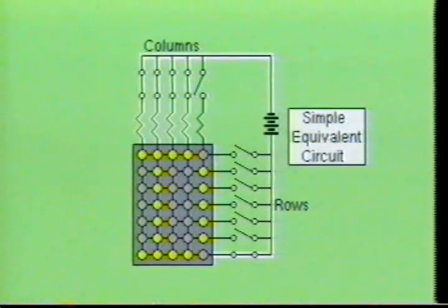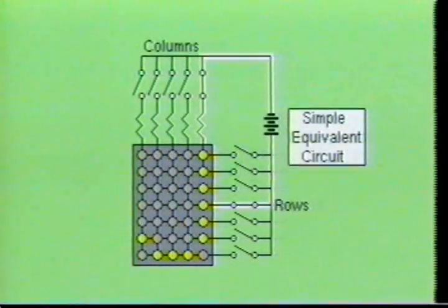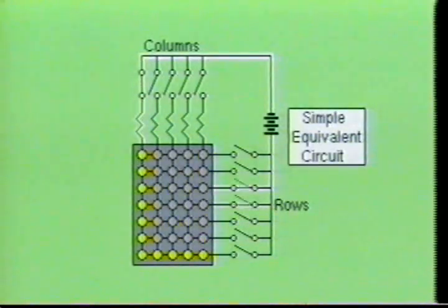As you have seen, the individual LEDs are controlled by the inputs being placed at the row and column inputs. The dot matrix display has become popular due to its ability to display both alpha and numerical characters. The dot matrix unit also has the ability to display many other common symbols. Most character generators have the ability of providing 64 characters. The 64 characters displayed by the dot matrix unit are contained in a read-only memory, which is contained in the character generator IC.